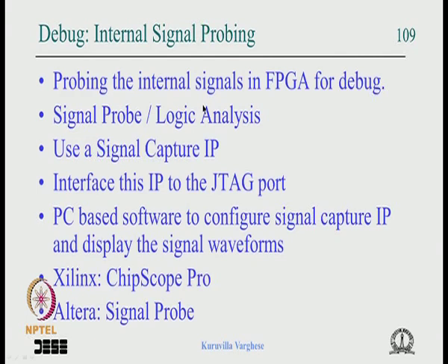And one other very important thing with respect to FPGA, so I'm discussing all what is remaining. One problem with the FPGA is that you have designed something in FPGA, you have verified, you have done behavioral simulation, timing simulation, everything, but the moment you put that design in FPGA, for whatever reason if something goes wrong, and if it is an internal signal, you cannot debug it, you cannot see what is happening inside.